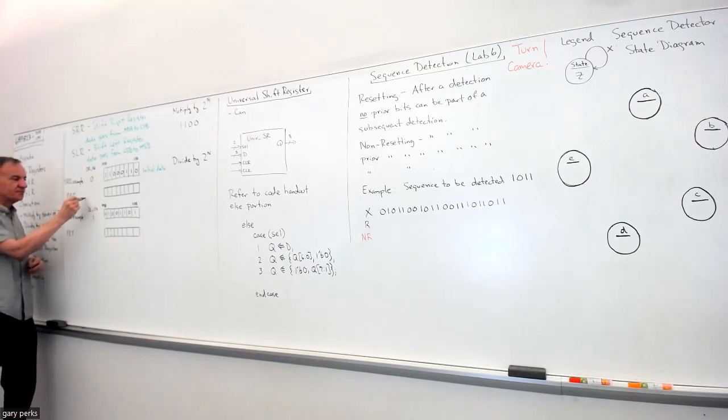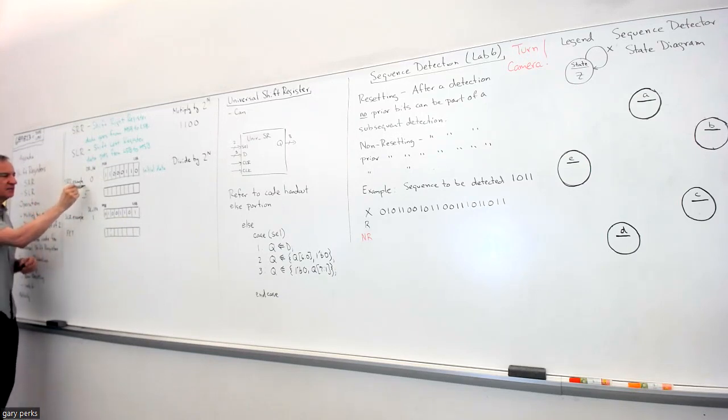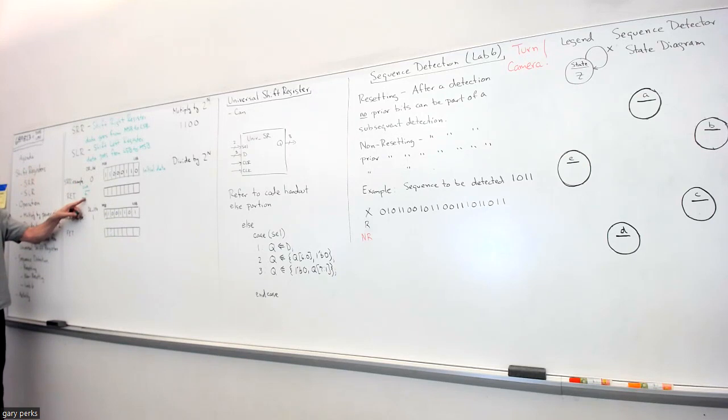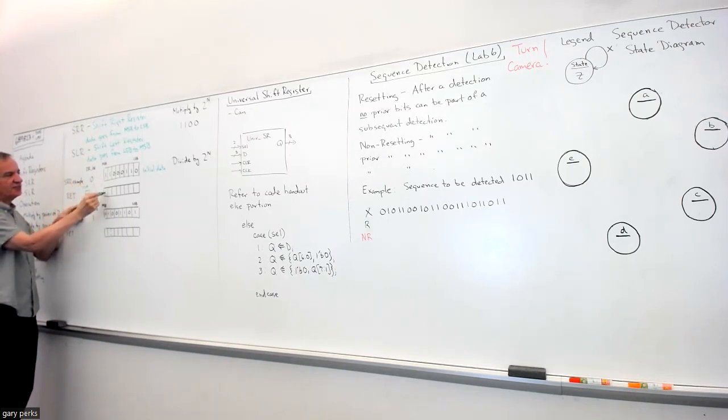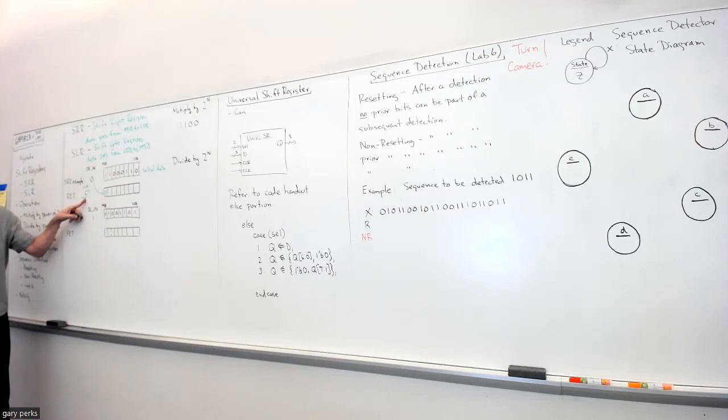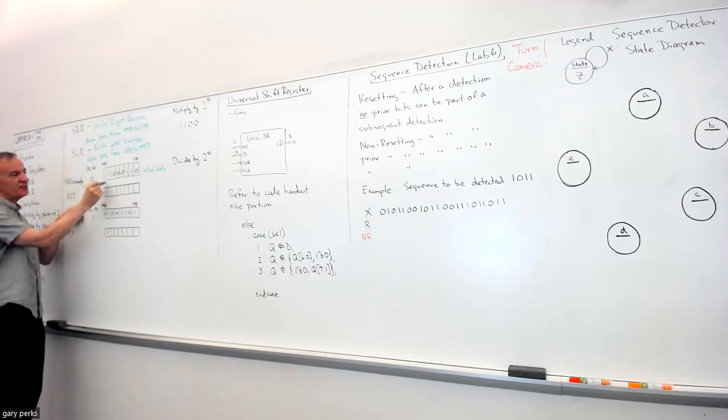So, okay, when the clock transitions from a 0 to a 1 at this time, since this is a shift right, the data on the DR_IN is going to go into the most significant bit of the register, and then all the other bits are just going to shift over one place.